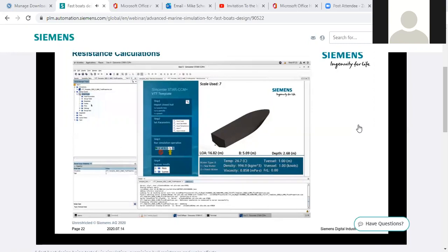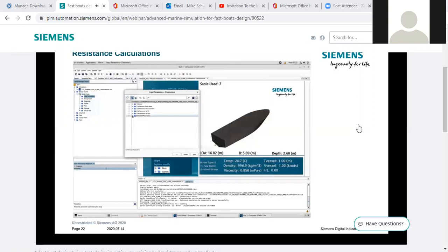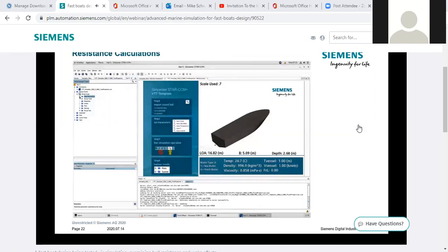So here we'll do a sweep, and then what we will do is we just simply select, in this case, the vessel speed. And now we want to run a range of speeds for this vessel. And in this case, we can go from 10 to 24 knots. And if we did 0.25 knot increments, it would be 57 runs. It's a little too many. Let's just do 4 runs. And then it's doing 4.6 knots.